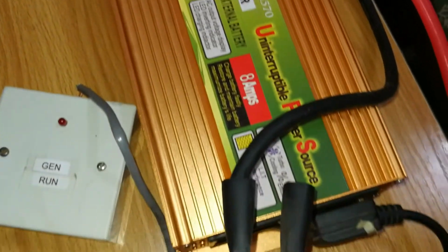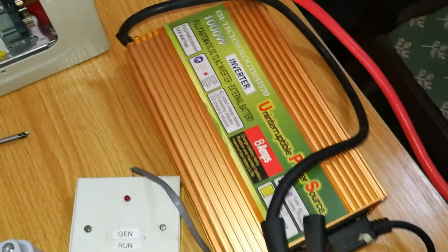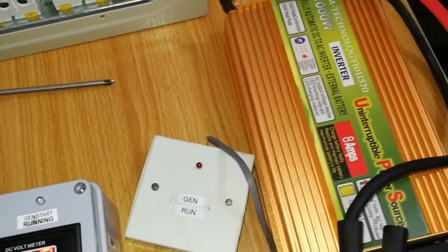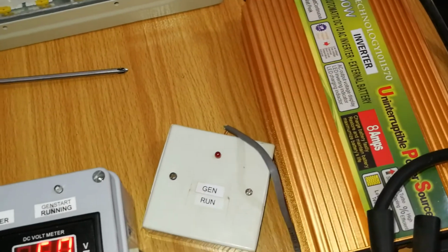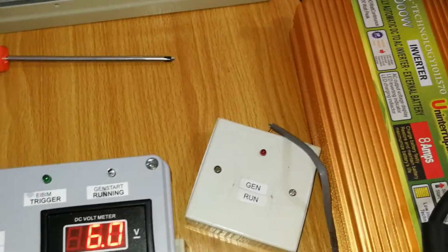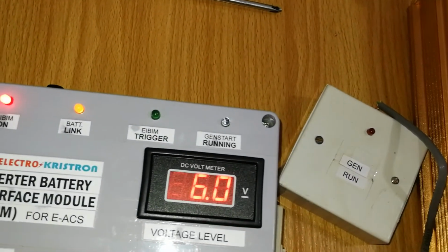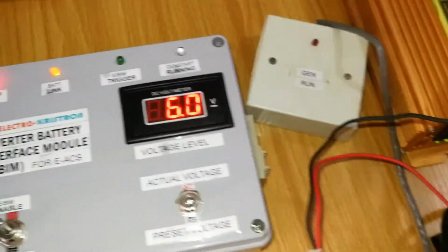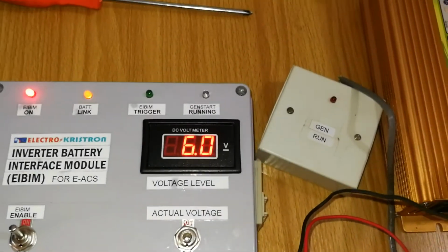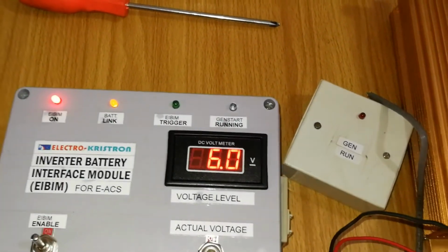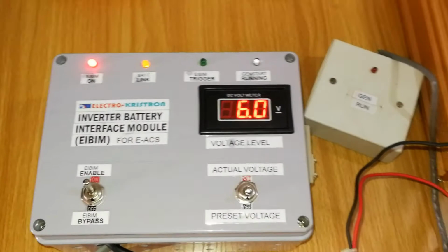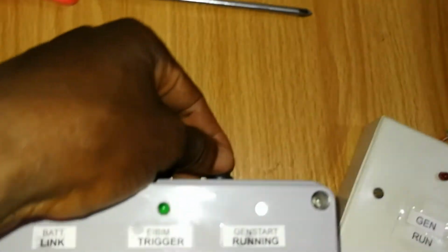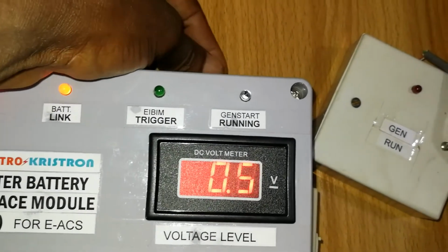Inverters are sensitive in their own way, so if you discover your inverter starts beeping when your batteries have drained to 11 volts, then your setting will probably be 11.2, yes, or 11.1 for your threshold setting, so that once it is 11.1, before getting to 11 volts, the gen will start running. Okay, so you need to experiment with this to know which value works best with your inverter,